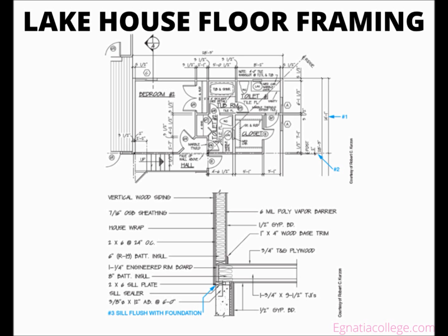The doubled smaller LVLs support the loft. The LVL beams form part of the roof framing. All of the LVL beams rest in beam pockets that are welded to the posts. The structural steel channel, C 8 x 11.5, is bolted directly to the posts.